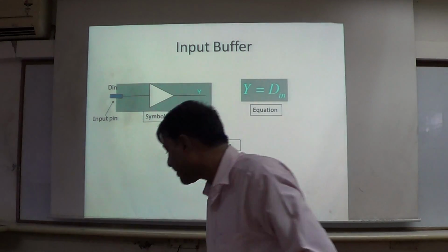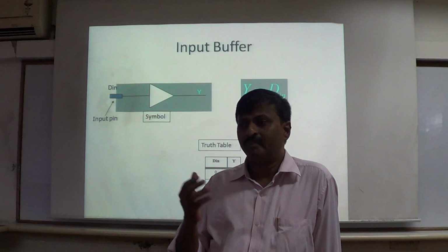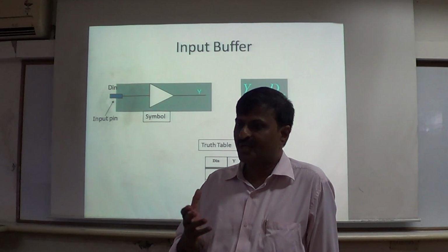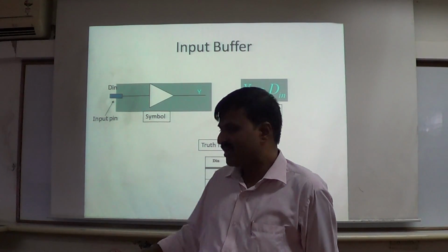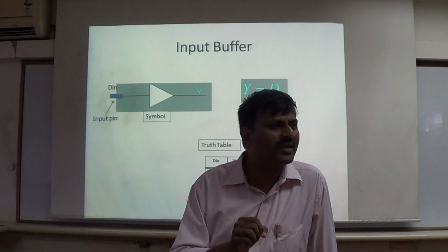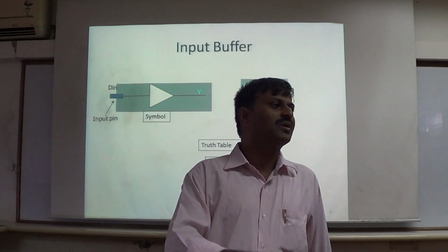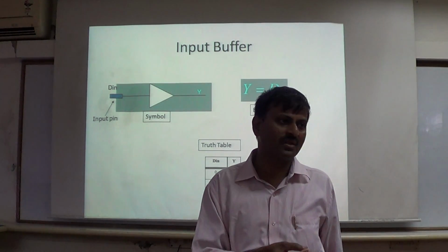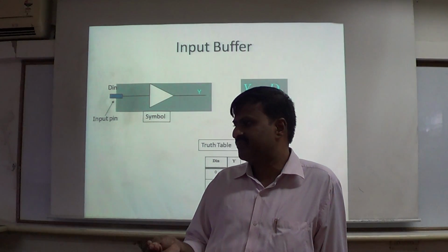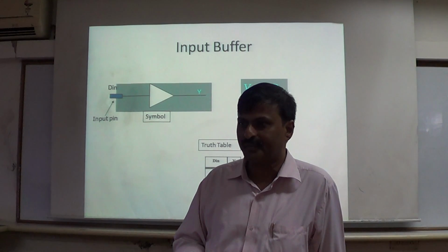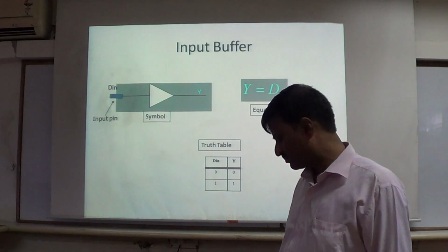So what happens is, this motor may be half ampere, maybe 1 ampere, 2 ampere, 5 ampere, but I am controlling it by my microcontroller, which is working on 3.3 volts. The amount of current, as we have discussed in digital electronics, that it can source or sink is hardly around 4 milliamperes or 16 milliamperes. So how to control these motors?